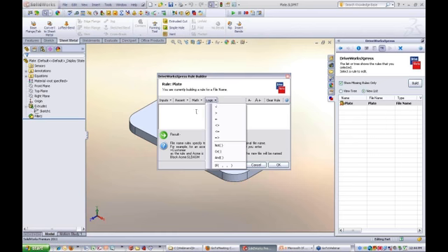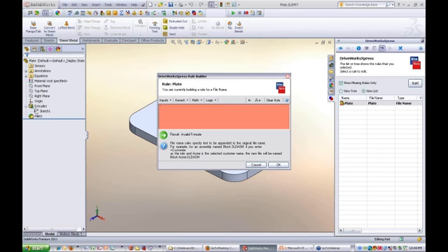In this case, I simply want to have a dash. Now it's straight text, so I surround it in quotes. You can see it goes pink when it's an invalid rule. That's okay now. I could have a dash after my word plate, but I also want to add to that. So I use the ampersand to say I want to add some text to it, and I want to add the project name. So every time I create a new plate, it'll be plate-project name. The result down here is empty, merely because there's no project name to display yet.